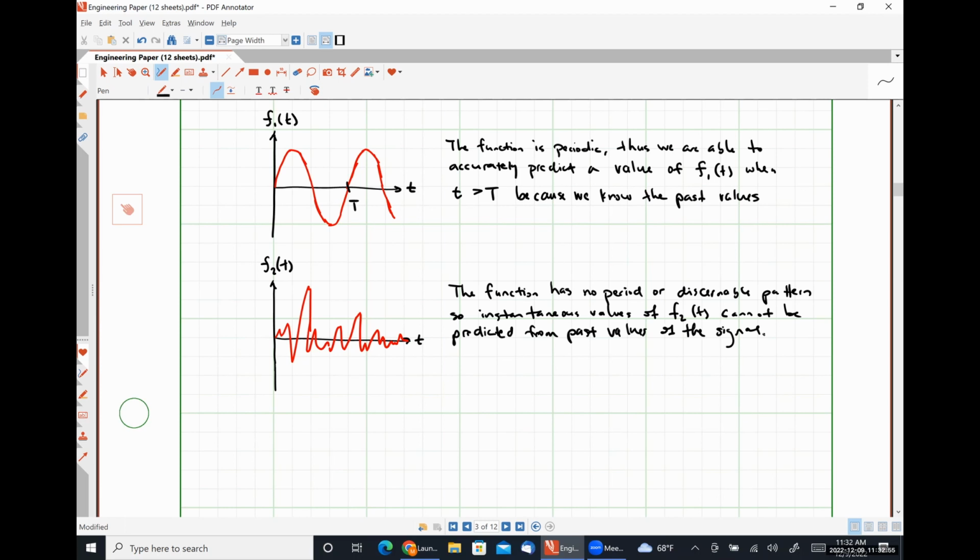All right, so if noise is a random process, how do we analyze it? Okay, so while the instantaneous amplitude of a noise cannot be predicted, it is often the case that the average power of the noise can be predicted. By observing the noise for a very long time, we can develop a statistical model for some particular noise sources. So this largely has to do with the fact that the overwhelming majority of noise sources obey a simple Gaussian distribution. Not all of them by any stretch of the imagination, but most of them do.